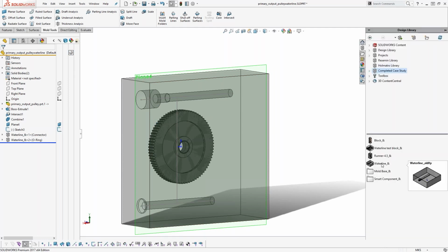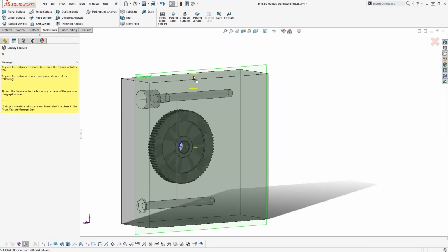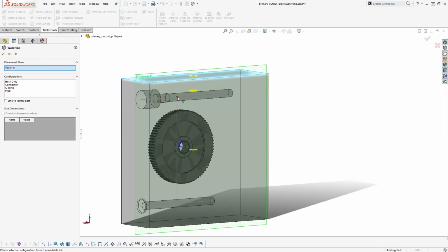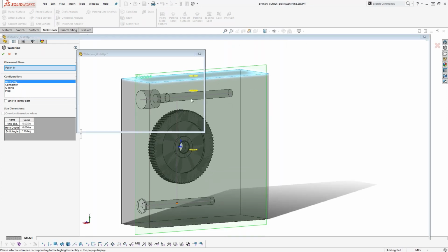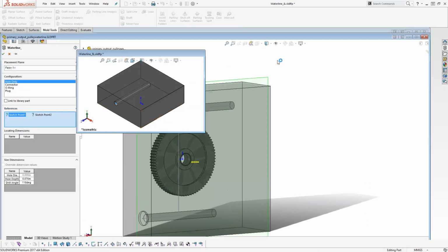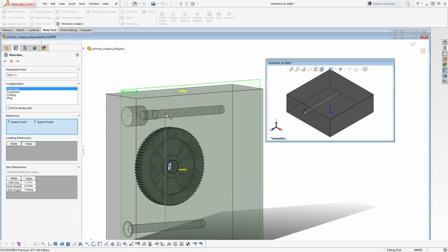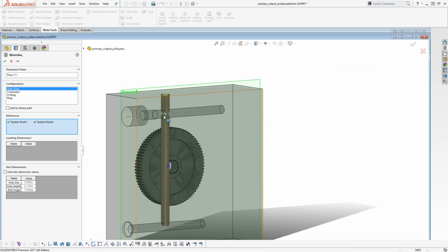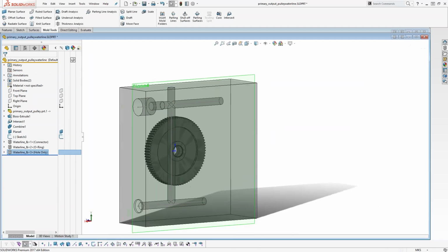These are really easy to make. We go over how to make these in our Essentials class. We're just going to drop them onto there, or we go over how to make library features in the Essentials class. These specific mold tools, this is in the mold tools class. So I'm just going to drop this library feature in here. You can see with a simple drag and drop onto a face and then selecting 2 points, I'm going to get that geometry that I was looking for.